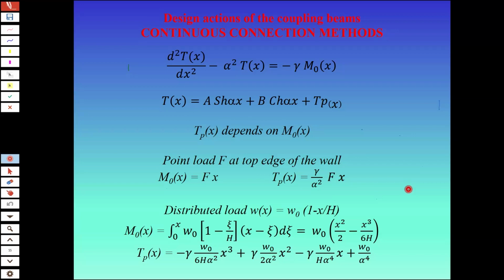And these do not require any special tool, any software. Just do it. Then if you do this, your software will provide you the answer, but you already know why that column is overstressed. Probably because I gave it an area which was very, very close to the minimum one, so probably I can enlarge that a little bit.